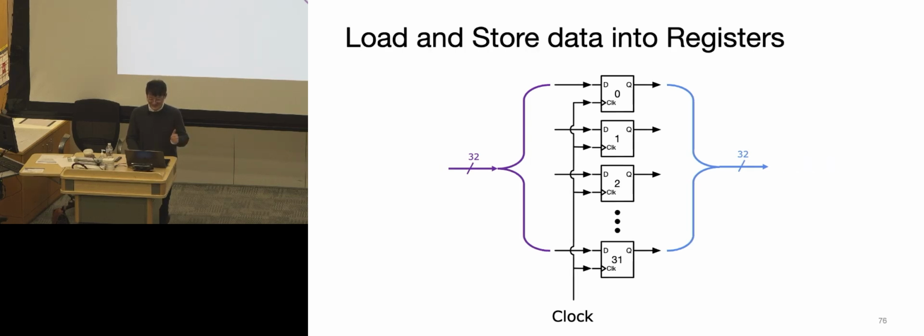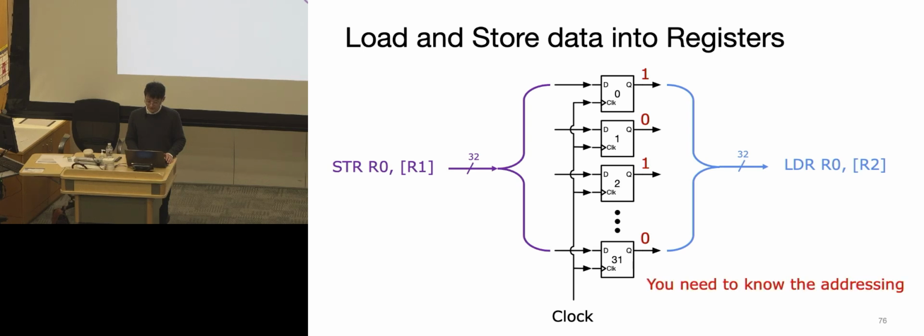Okay, and same with the storing. Data comes in and then the registers, and then it goes to be stored somewhere in the memories or sent out to other pins as the output or other peripherals, anywhere in the system, basically. The only thing very important here is you will be knowing the address of each of the registers, like where exactly, or in the memory, you need those data to be. And these can typically be found in the data sheet.